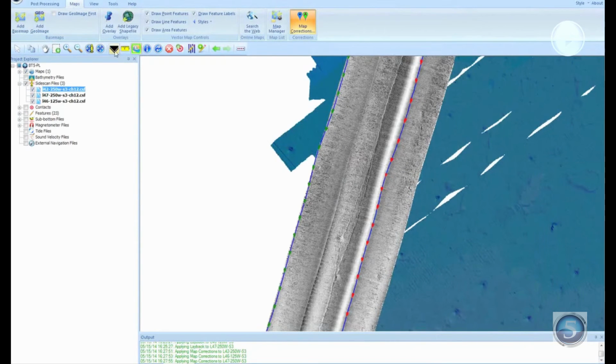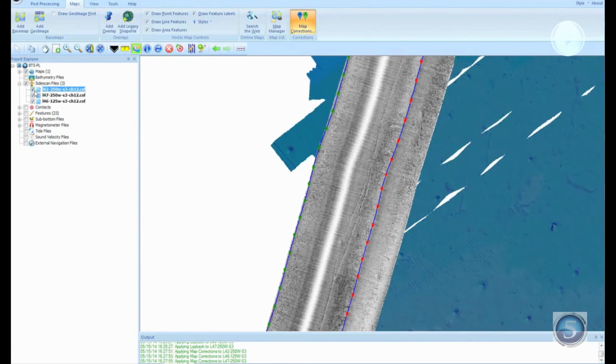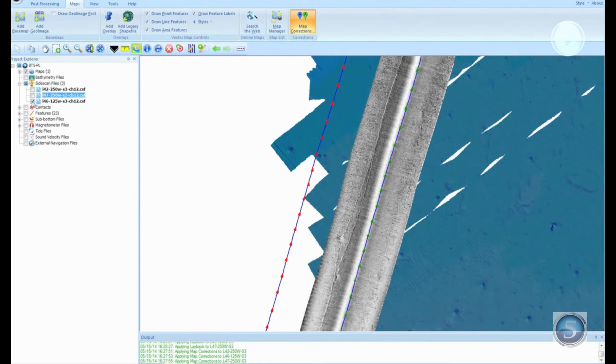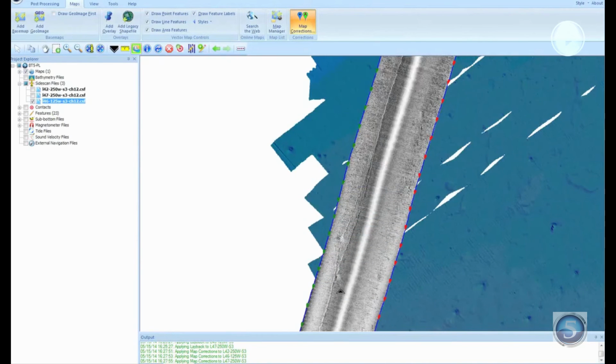And look at that. These lines each agree with one another now. You can see these features show up in all of them. See the little pothole, pockmark in the same spot. And finally, if you want to see how it ties in with the multibeam, there you are. So you can see you can add another point there and improve upon that, make that pockmark show up a little bit better. But the beauty of this is you can do it to as many points as you want with as many side scan lines as you want, and it'll correct the position for you.